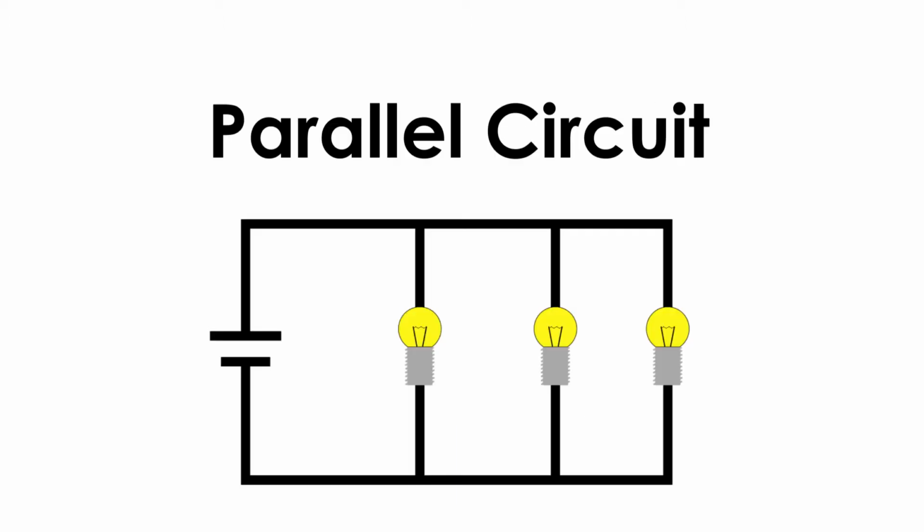When items in a circuit are connected to the power supply along separate branching paths, they form a parallel circuit. In parallel circuits, the current is divided up across each branching path, each resistor in the circuit receives the same voltage, and the resistance values of the resistors are tallied up by adding their reciprocal values and taking the reciprocal of their sum, meaning that the total resistance of the whole circuit will be less than the value of the smallest resistor.